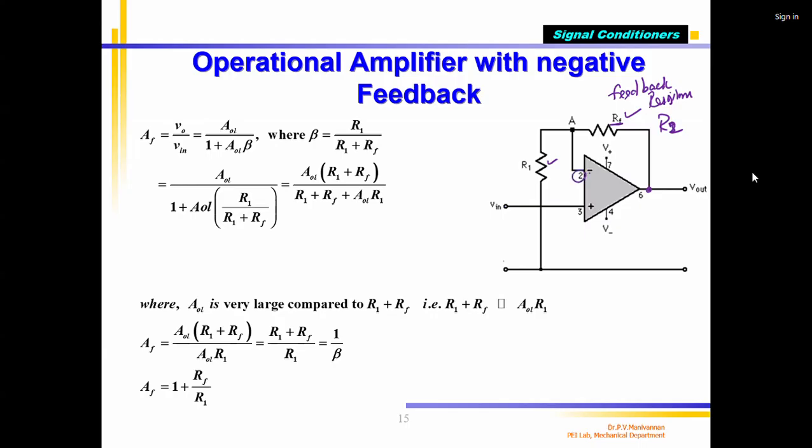In this case, pin number 2 of the 741 is the inverting input. You can see that this resistor RF is connected there. Then one more resistor, which I call R1, is connected between the inverting input and ground. Ground equals 0 volts. This circuit is called the feedback network. These 2 resistors, connected from output to input and to ground, with the center point going to the inverting input. In an operational amplifier with feedback, the output voltage is decided by these 2 resistors only. That's what we are trying to prove.